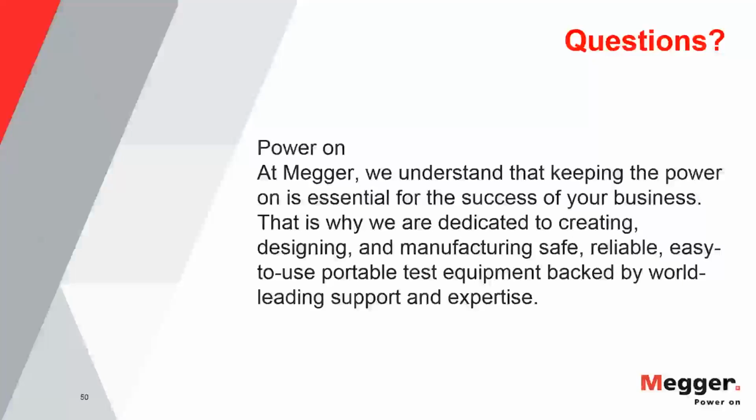So, yeah, they're here, but the basic idea is that for extruded cables, XLPE and EPR, it should be PD free up to twice rated voltage. There should be no detectable PD. That criterion isn't really practical for aged cables.